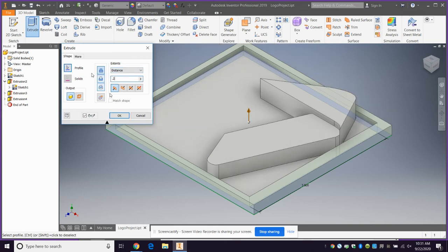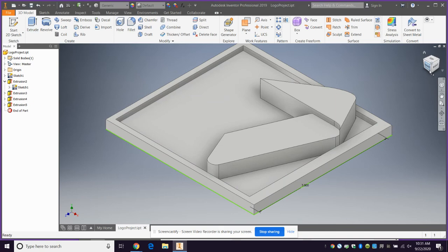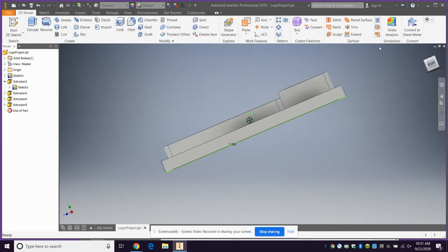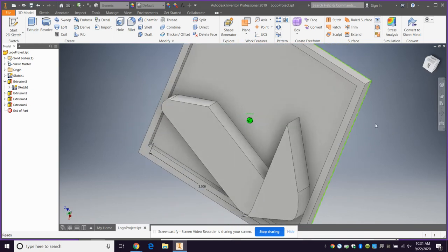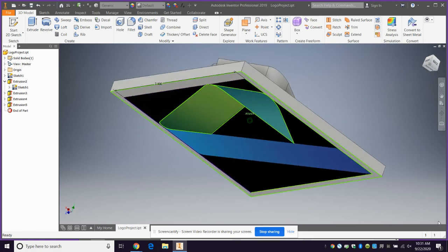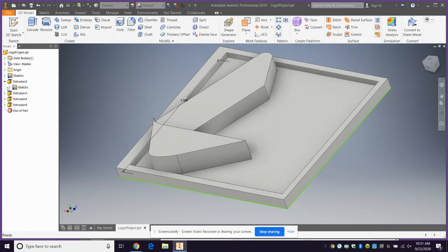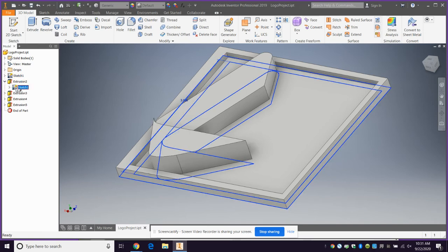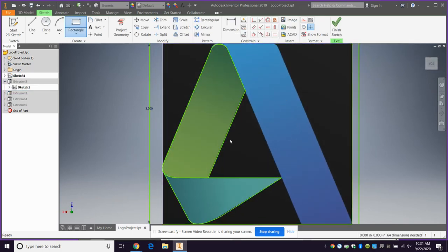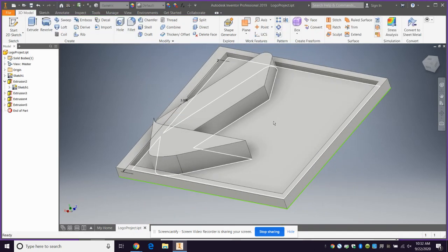You can see how we start to build this, right? So you draw these shapes, you extrude them. My sketch is still in there. It's covered over by the model, but I can still go back and extrude, and I can finish out that at A. All right, finish sketch. And there we go. And we continue on.